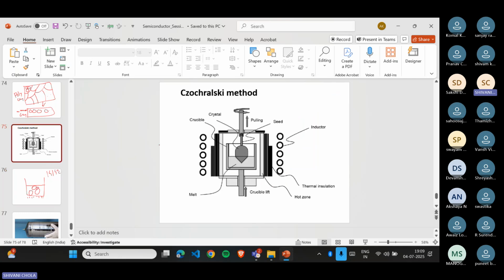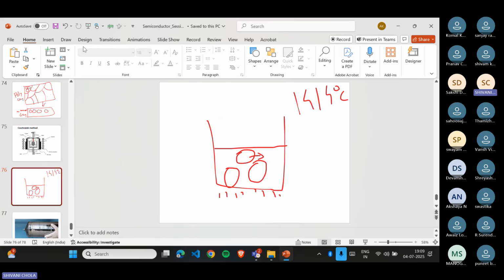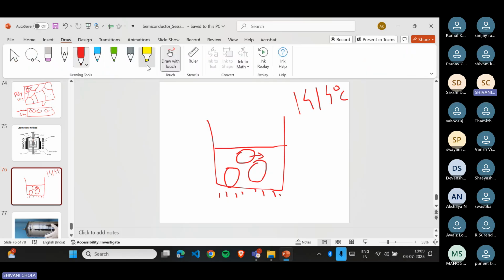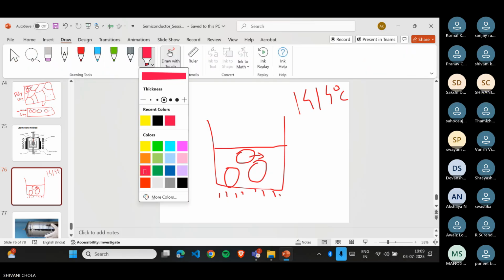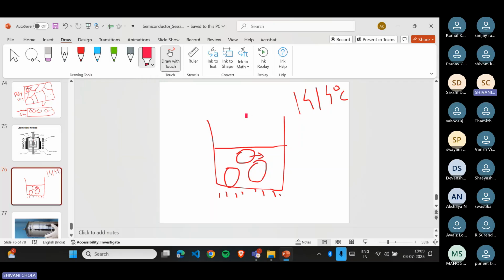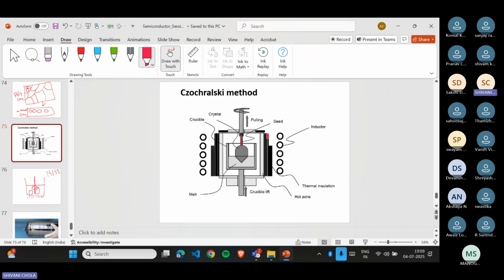And once all this polycrystalline silicon is in melt form, you put in a small pure silicon crystal. This is a pure silicon rod, a monocrystalline silicon rod. You put this small rod inside this liquid. So let's imagine this is our pure rod. You dip the pure rod inside this melted polycrystalline silicon, and you start to rotate this pure rod around its axis.